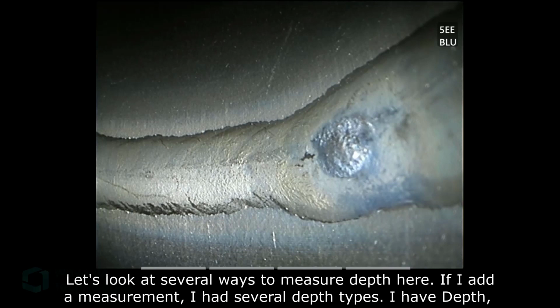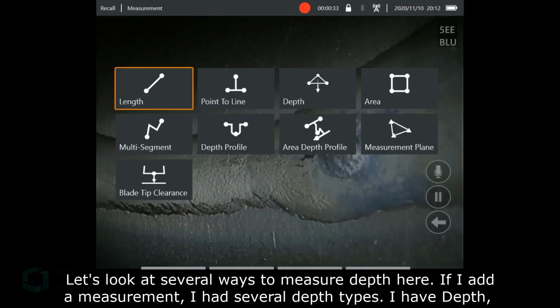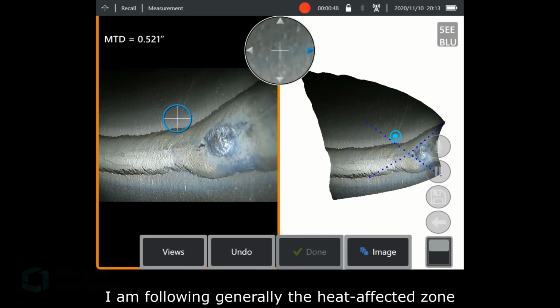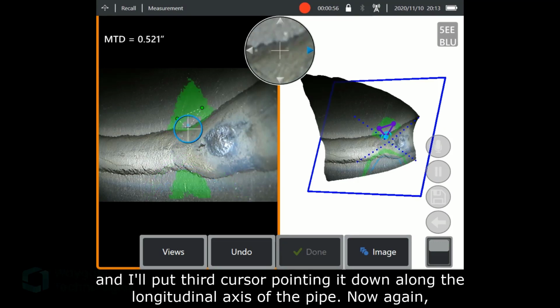If I add a measurement, I have several depth types. I have depth, depth profile, and area depth profile. Let me show you how you might use depth first. So again, I'll establish a mathematical plane with 3 cursors. I'm following generally the heat affected zone, and I will put a 3rd cursor pointing it down the longitudinal axis